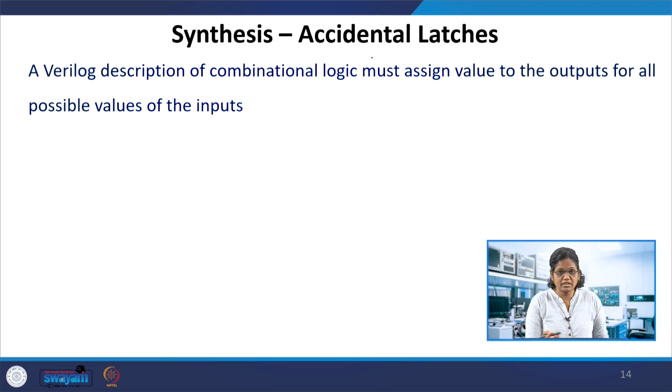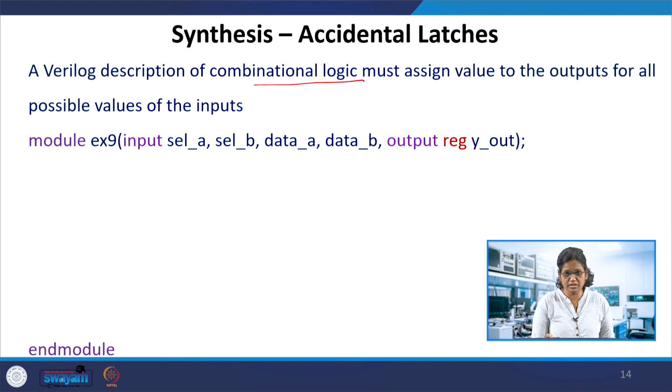So, the accidental latches: consider in what cases these accidental latches can occur. If the Verilog description has to be realized as combinational logic, then it should have an assigned value. For all the possible inputs, the corresponding output should be specified, otherwise it would infer latches.